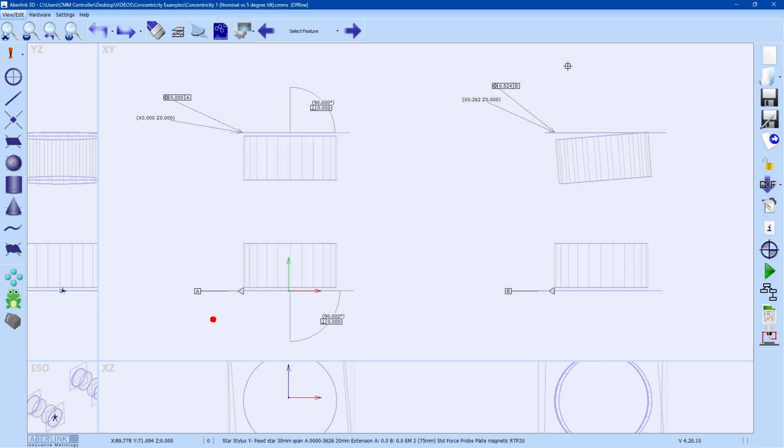This is all working well, but the dilemma whenever there is an axis tilt, which is what we're trying to check, is that the depth at which we measure the circle on this bore will have a massive effect on the concentricity. As we go deeper and deeper into this bore, the projection of the circle will shift along to the right, and it gets worse and worse.